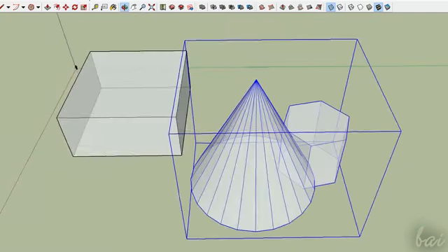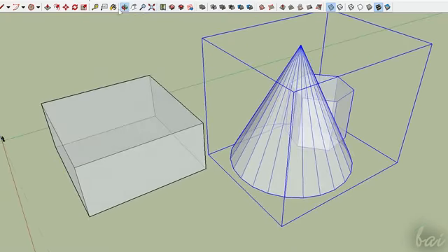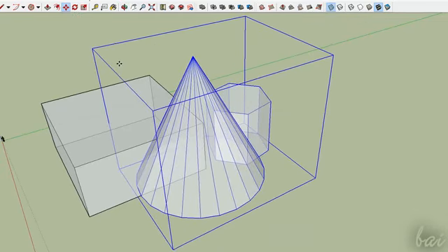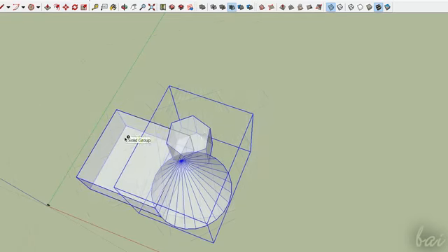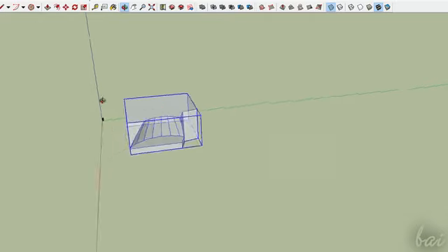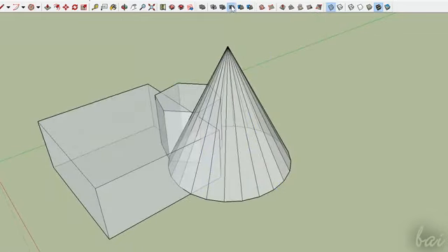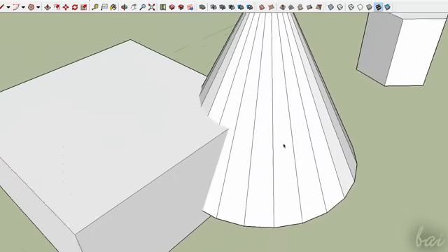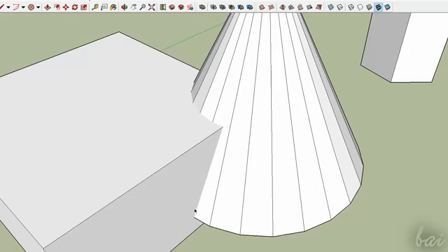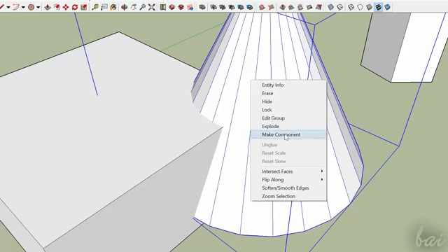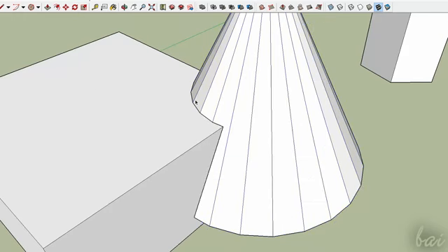If you need to work with more than two solids, you must create a group that contains more solids, and then you can go on using the tool. Don't make groups that contain other groups, or tools may not work. Moreover, if you want to obtain contours without editing solids, you can simply right-click on the overlapped solid and go to Intersect Faces with Model. Contours are added as simple lines, as you can see with the Select tool.